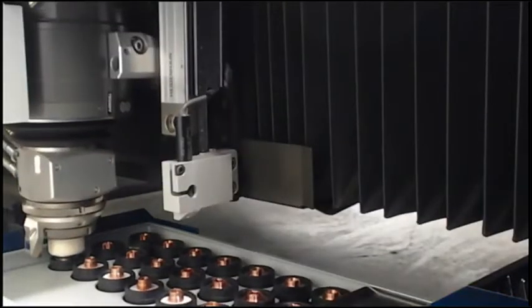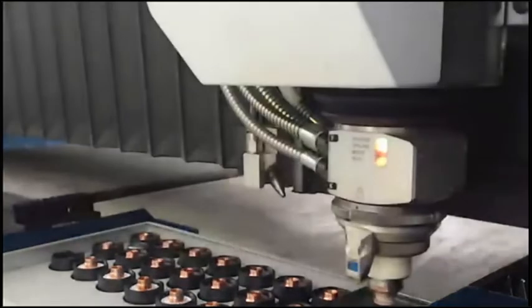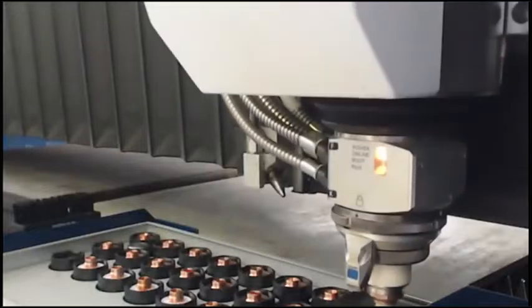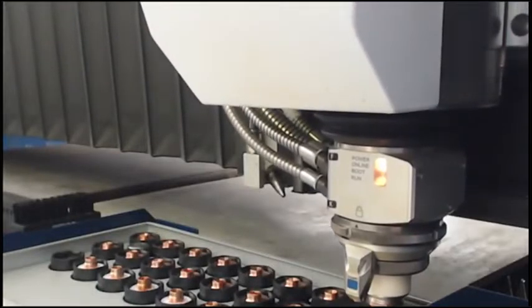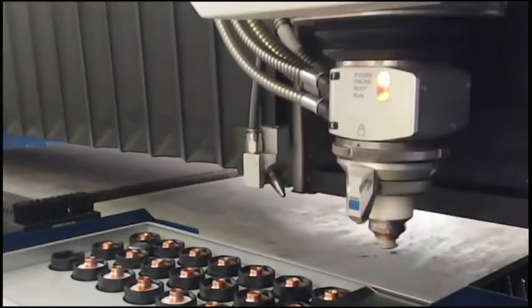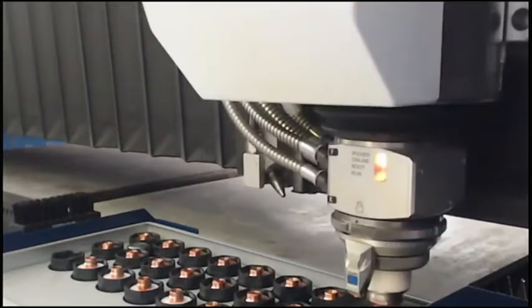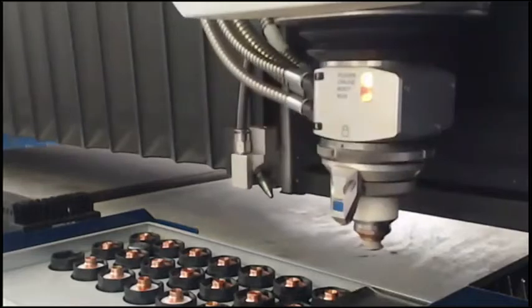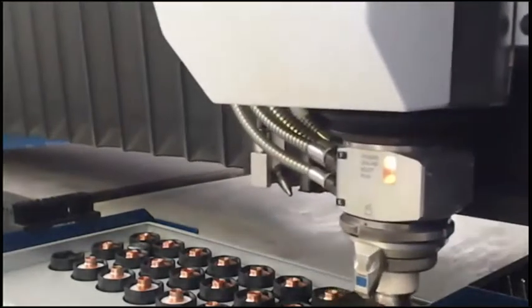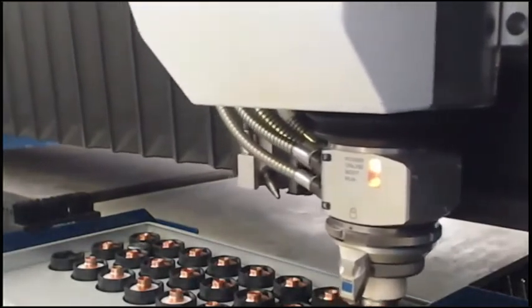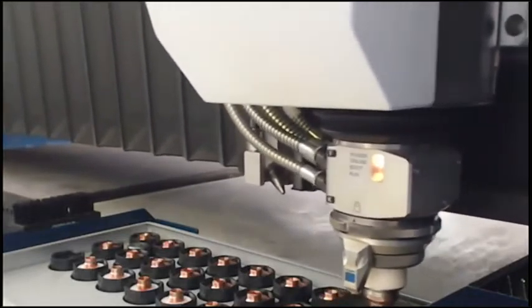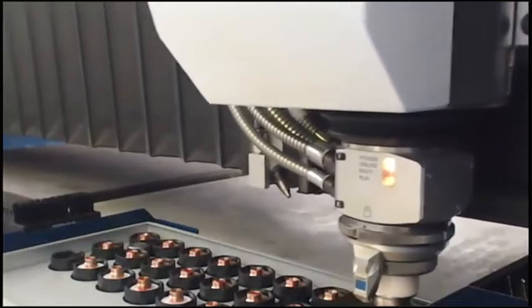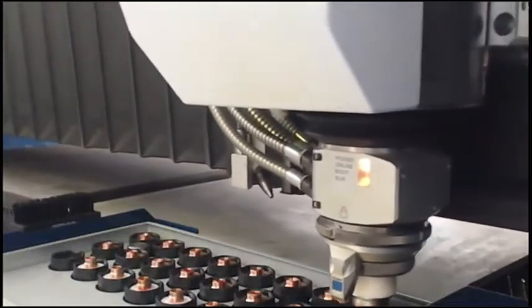You'll actually notice that on some of these nozzles, it'll do a little bit different of a control line calibration. You'll see it kind of swirl around. It's actually calibrating that active speed control that Brett was talking about before. So a little tidbit in there. Cool thing about this nozzle, we use it for a lot of different scenarios. It's gonna work from 160 thousandths of an inch to 1 inch stainless. It's gonna work from 160 thousandths of an inch to 1/2 inch steel on this 12 kilowatt laser. Same thing goes for the 10 kilowatt.